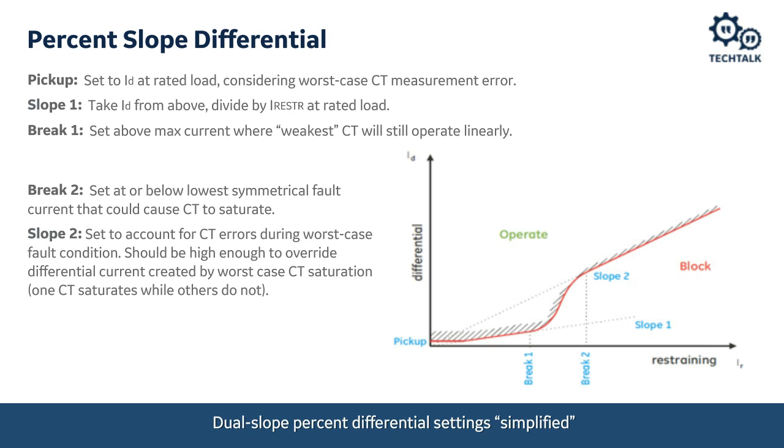You can modify the fault current value until you see a good half cycle of saturation-free measurement, and then use that fault current value as the breakpoint 2 setting. Again, a really good example of this, along with screenshots of the IEEE tool, are available in, in this case, the 845 relay manual.